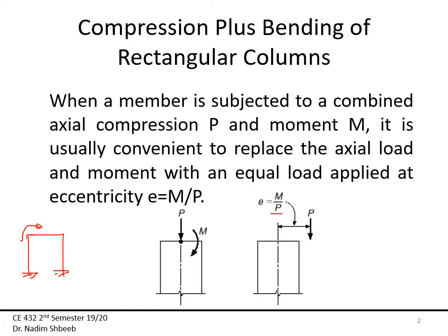And as you know from strength of material, which define eccentricity as being the moment divided by the axial force. Eccentricity could also come from lateral force, which again will create a moment for me, and that moment will again create an eccentricity. The other part is due to the load being not physically at the centroid of the column.